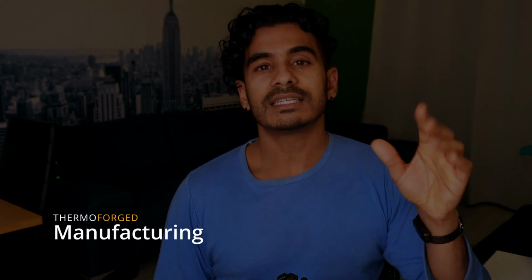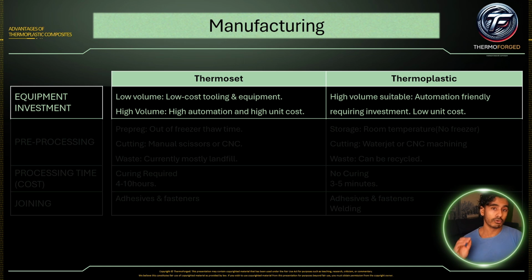Now, thermosets are brilliant for low volume. So if you're making a couple of parts, thermosets are easy and cheap to process. But if you have a lot of parts to make, thermoplastic composites are brilliant for automation, therefore automation friendly, and then you invest the money and you can make a lot of parts at low cost.